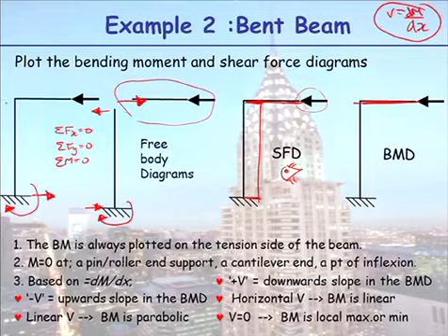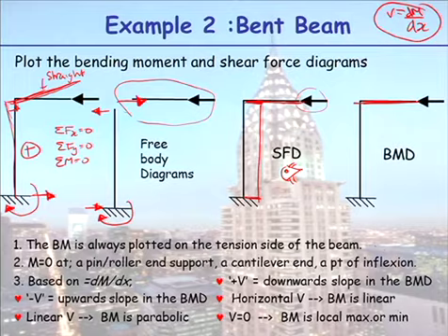Is there any bending moment in this horizontal leg? No. Okay. Can you imagine how this thing deflects now? It's off the screen, so I won't draw it deflecting too much. And I'm exaggerating. This bit here should be straight. And it's just tilting up because this thing is bending. So the corner has to remain at 90 degrees. So my bending moment, what side have I got tension on? The right side.